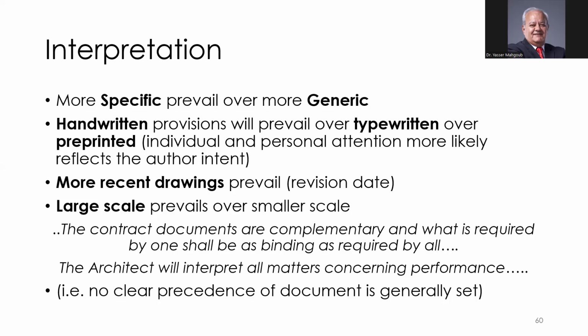Handwritten provisions will prevail over typewritten and pre-printed, as individual and personal attention more likely reflects the author's intent. Usually we consider the handwritten more important than the typing because it came later, after the typing of the specifications. More recent drawings prevail.